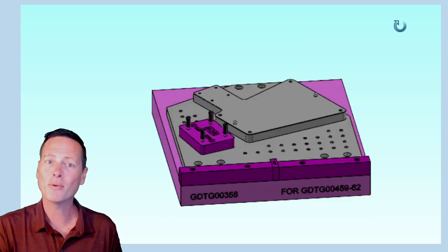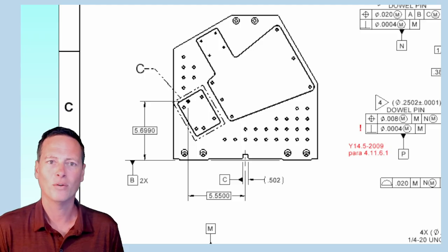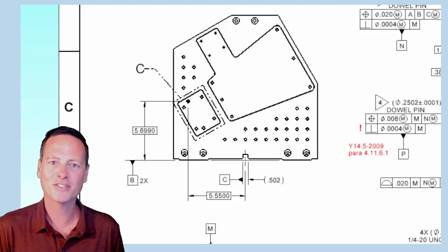But of course, if we were to do our inspections on this bad part, it would still pass, wouldn't it? I can hear the howls of protest now. That wouldn't happen. Everybody knows my intent is that the pattern would have good orientation control, and so on. Save it for someone who doesn't go on the internet calling himself the GD&T guy. It's underdefined. Go read in the standard, the fundamental rules A through D. This is section 1.4.